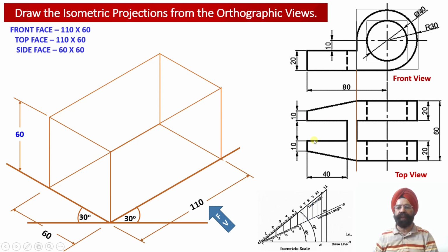20 millimeter over here. So now we know that corresponding to this element number 1, which is a horizontal web, this has a length equal to 50 millimeter and height equal to 20 millimeter. So now this 50 millimeter by 20 millimeter block we have to draw towards the left hand side face of the solid.